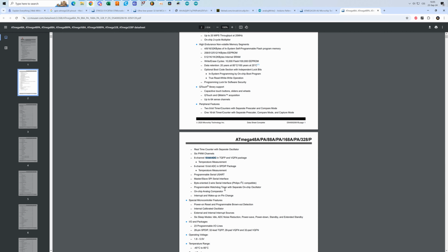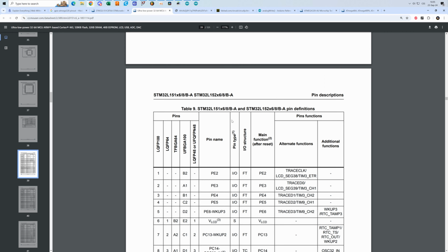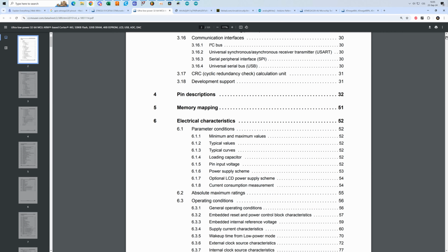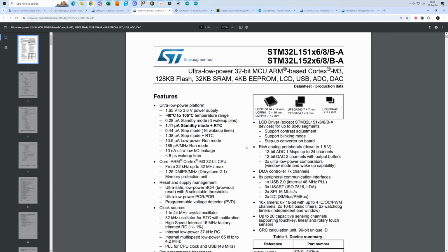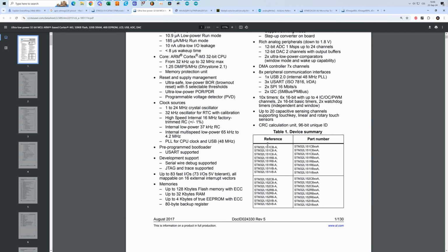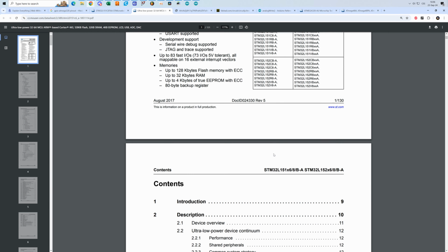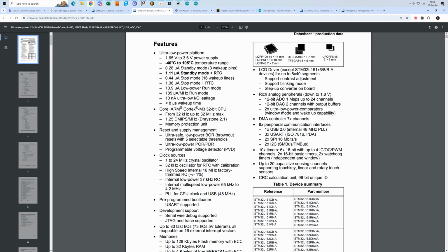Of course, on chips like the STM32, this is going to be way, way better. They are built in such a way that they are better than these ATmega chips. And their ADCs are usually, you can see over here, 12-bit, so that's 2-bit better resolution, 1 mega sample per second. So that means we can use a sampling rate of 1 megahertz.